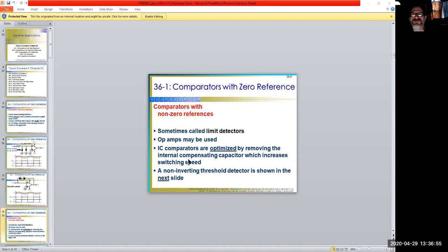They use them for a couple of different things. You could do this with other transistor devices if you wanted to. But the cool thing about using the op amp is that it's more reliable. The op amp can handle more without getting shorted out. And as you've seen with the decibel roll-off, we have a much better frequency response with the op amp, versus a transistor model where we would have a tight bandwidth. With the op amp we have a much wider bandwidth ratio, and that's why we would use the op amp for a device like this.